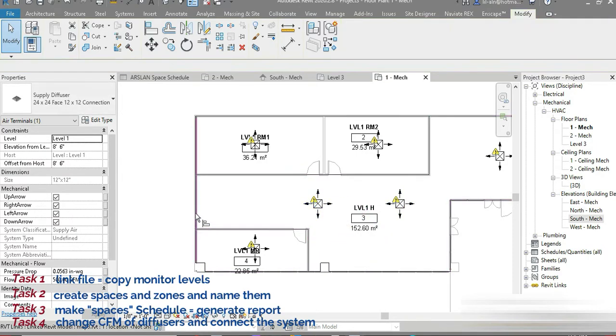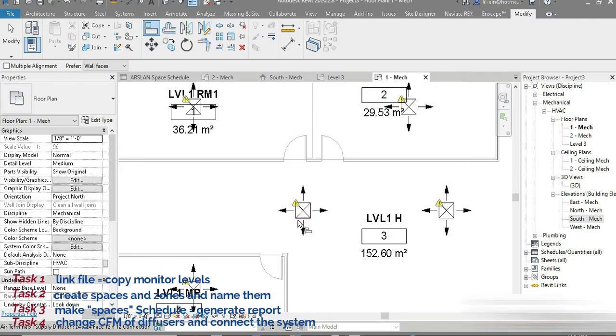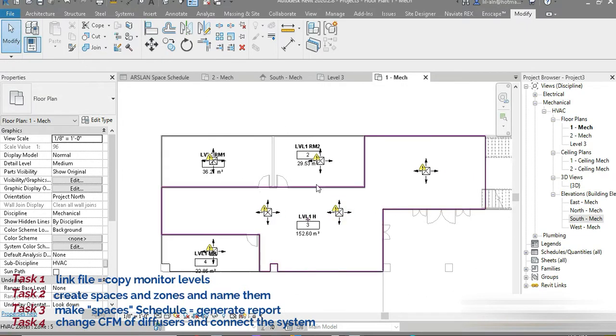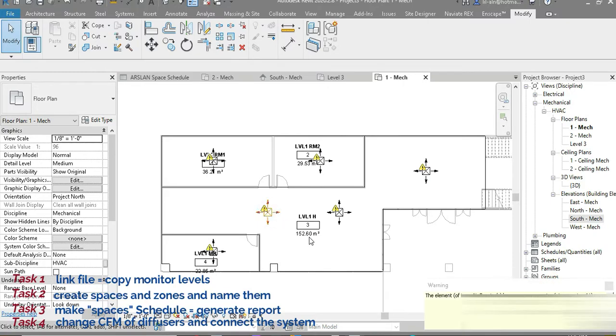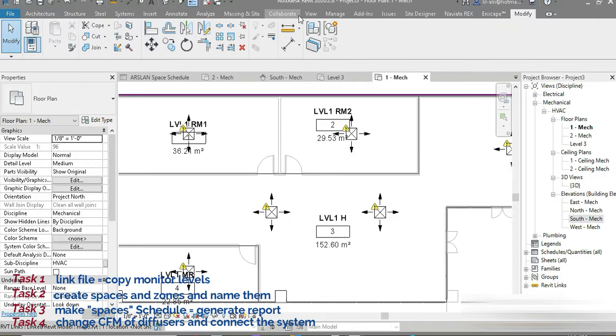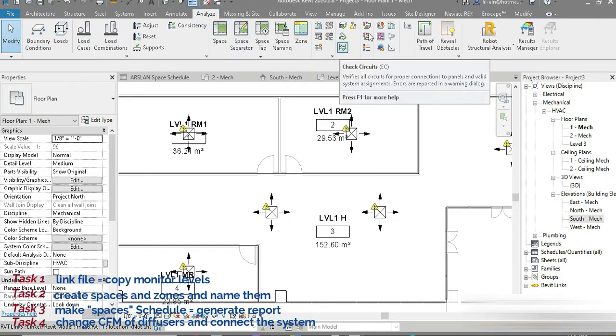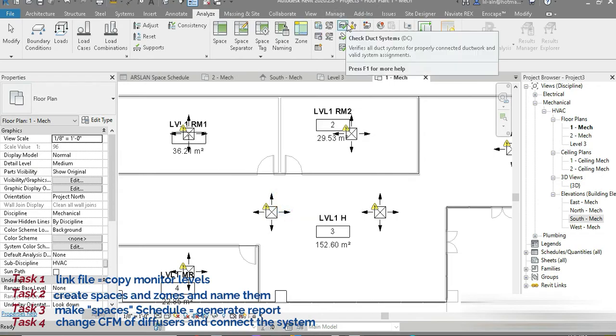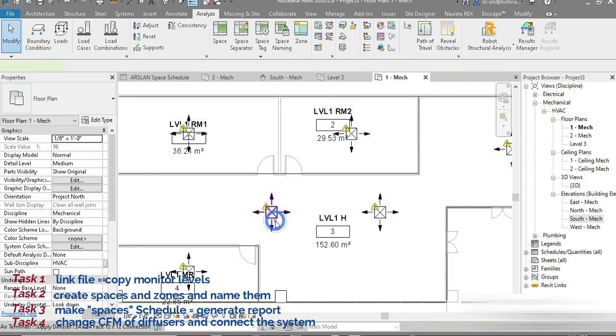After that, we can even use a line. Never use this 1, 2, 3, 4, 5 method, the one that I did. That's very unprofessional. So this is what we have, right? For example, if you click on that, the element has an open connector. That's fine. And these warning signs can be activated by going to Analyze, and this part right here, Show Disconnects. So if you press on that, this is a very awesome tool. It's going to show you all the disconnects that you have.